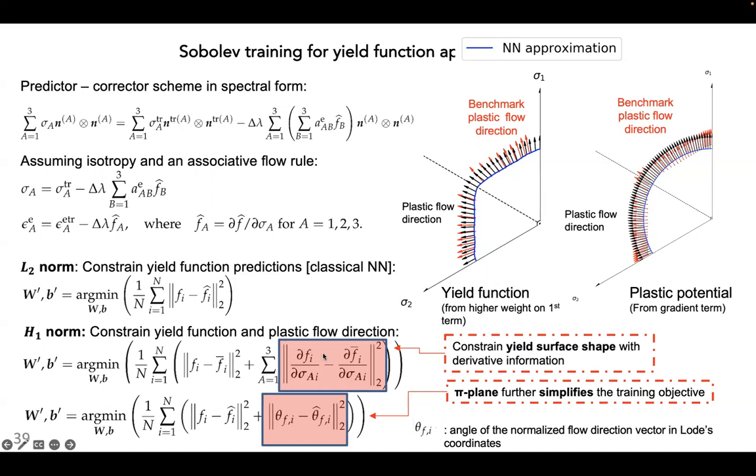Now, this is also something interesting for those of you who already took plasticity. If you can find a way to successfully train these loss functions using the plastic flow measure instead of the stress gradient of the yield surface, and this is successful, what it indicates is that by creating a more compact shape, I don't need the non-associative flow rule.